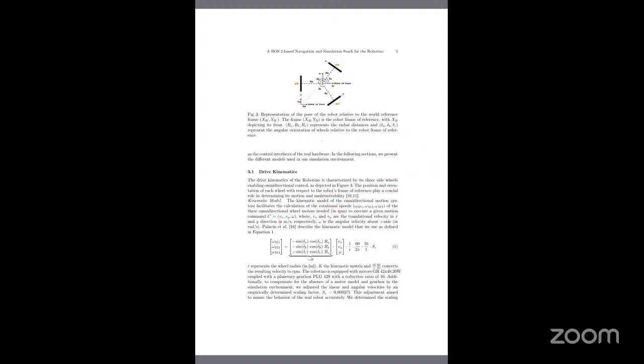And scaling factor. In simulation, we don't have a real motor, we don't have a real gearbox. Because of that, in simulation, the robot will move very quickly or slowly. For that, they have used a scaling factor, SSC, 0.009375.